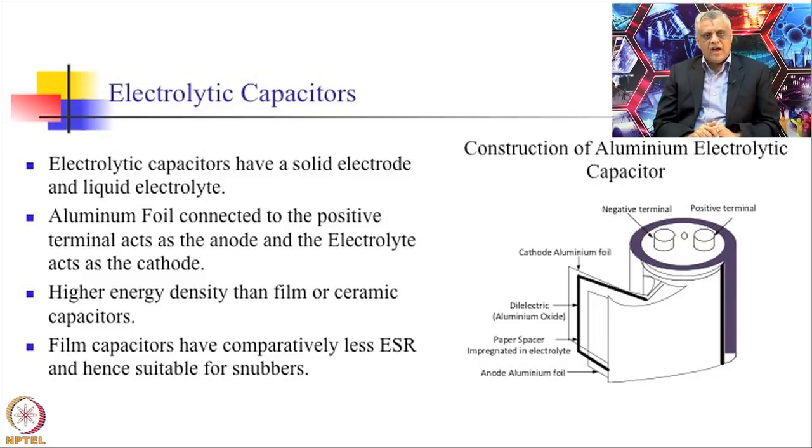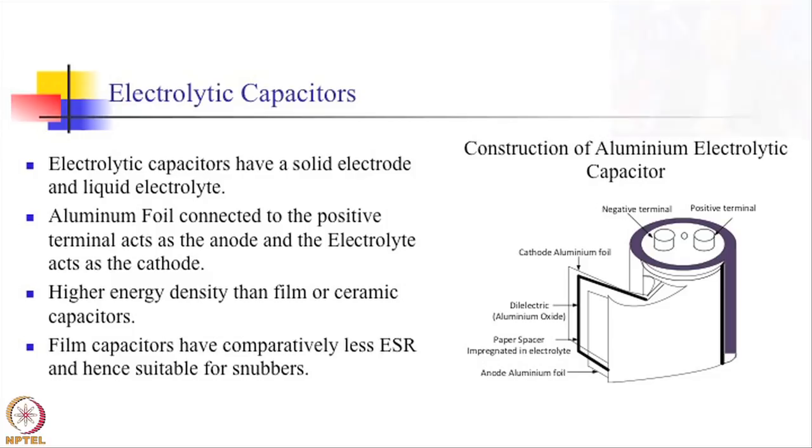So basically what you have is the etched aluminum foil, then next to it the aluminum oxide Al2O3 with a dielectric constant of 8.4, which works as the dielectric. Then you have the plate formed with the help of a liquid electrolyte, and then a second foil of aluminum coming in, which is in touch with this electrolyte.